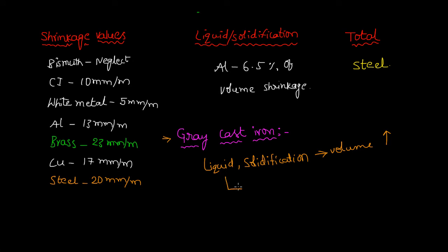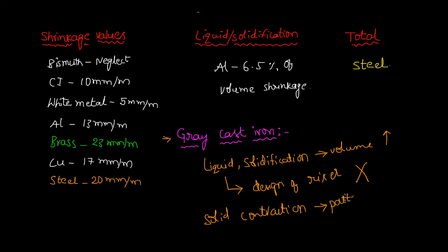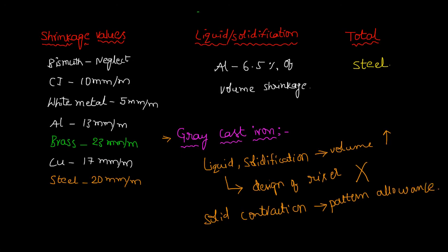That's why there is no need of designing a riser. It has only solid contraction. So by providing pattern allowance, we can make the product exactly.